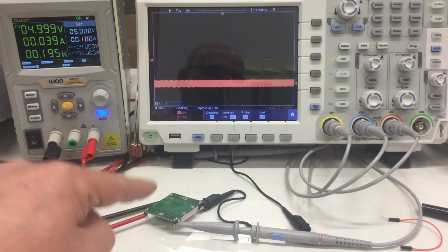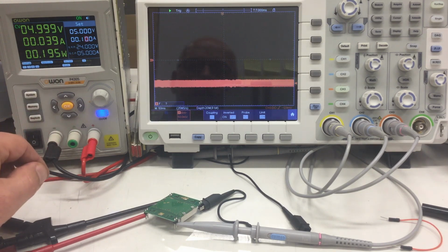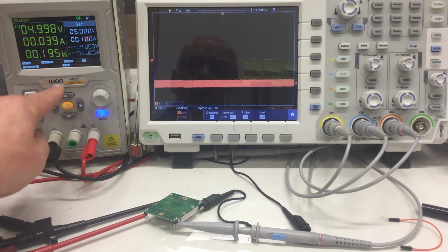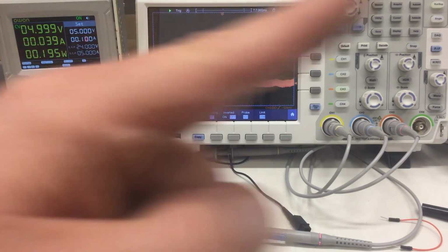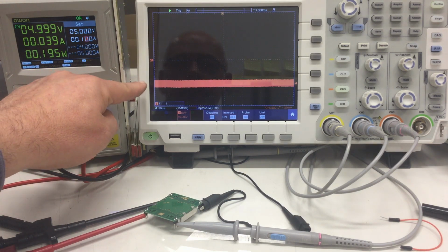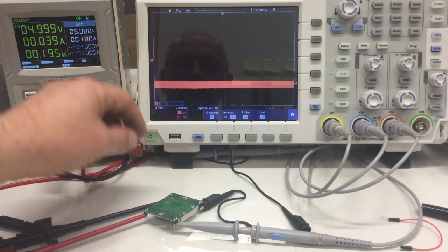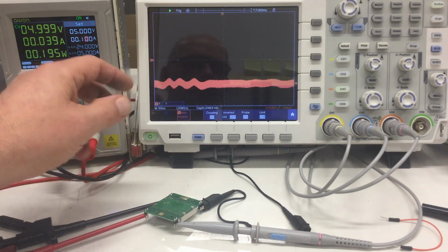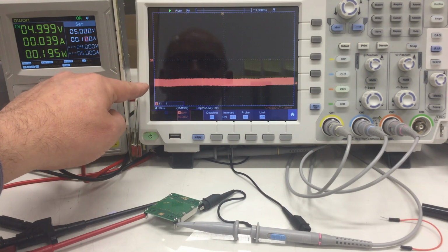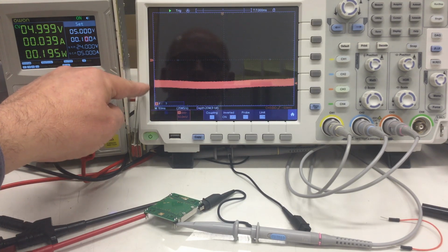But now let's play a little bit with such a module. So I connected it to a 5-volt supply, and by the way, there's an unboxing video for that over on the P4305 card link. And I connected the oscilloscope to the intermediate frequency output. And the first thing you notice is that the intermediate frequency output has a DC offset. And it's already working if I move my hand here. A DC offset of about 125 millivolts. And it's quite noisy.